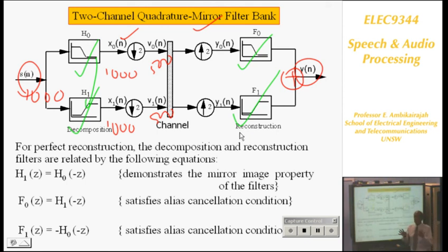You need to look at this two-channel quadrature mirror filtering theory, and what people have done is they've used these filters as wavelet filters, and these coefficients become wavelet coefficients. By modifying these coefficients and reconstructing, we can remove noise in the signal, all kinds of things we can do. So wavelet has become a different tool for various other applications. And the theory is what I explained, variable window. Variable window comes little by little when you go through this. Because of the subsampling, you change your window size.